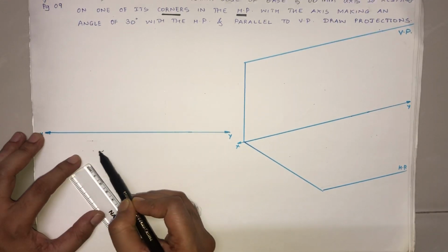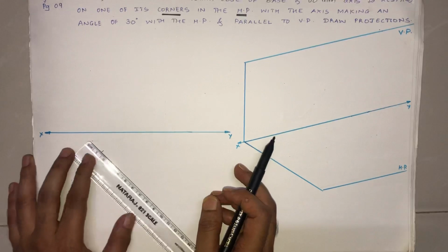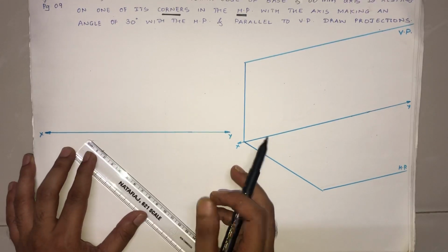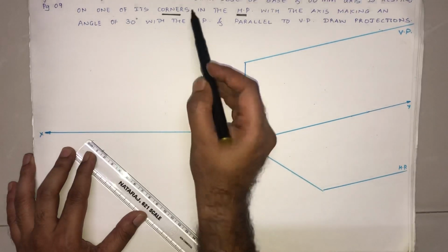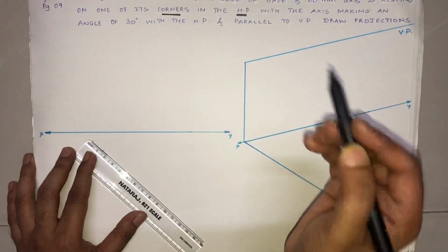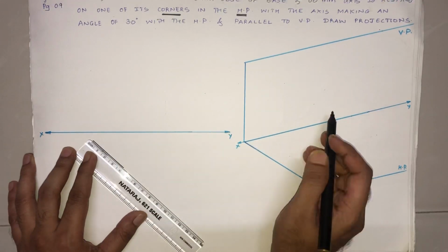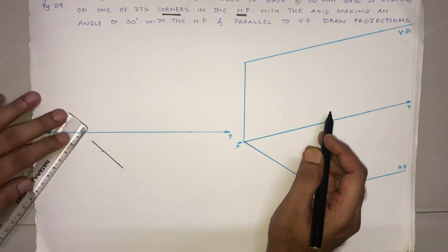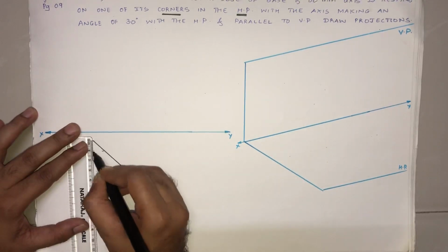This and this, I have kept them equal, 1 centimeter and 1 centimeter. Hence, this angle turns out to be 45. And that is a property of a square. I know that the base of a square is made up of base edges whose length I know, 40 mm. So, I'm going to draw 40 mm here, right? Similarly, on this side, I'm going to take, say, 45 again.